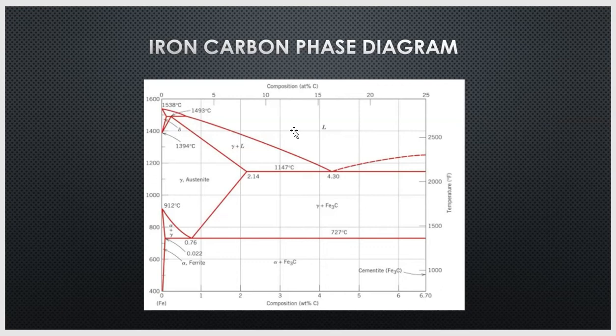So remember, this is where it's hardened, but its brittleness has also gone up, and its strength and ductility have gone down. Now, if you wanted to temper it, you again could find the carbon content of your metal, and that would tell you how high heat you need to apply to that piece of steel, bring it up to that point just below its transformation temperature, and then allow it to cool off.